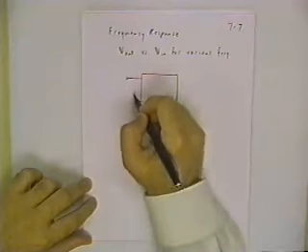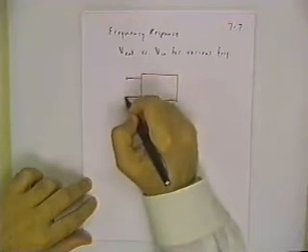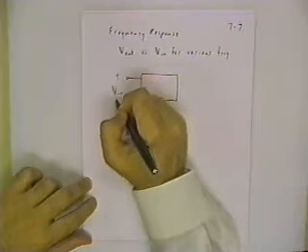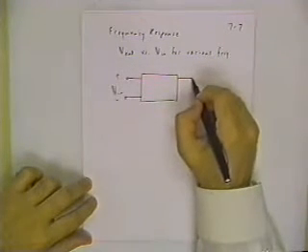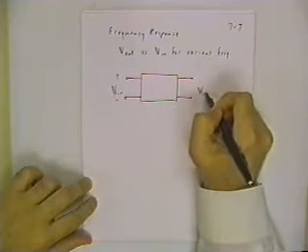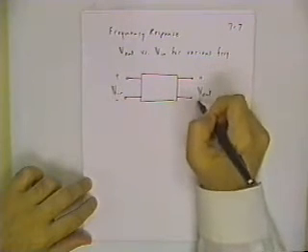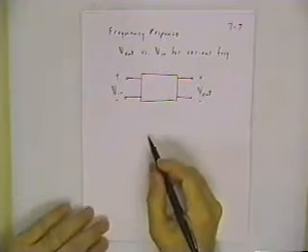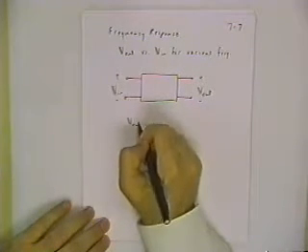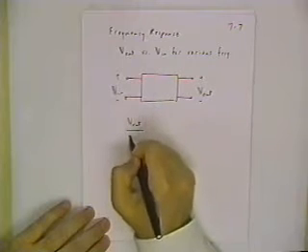At 2 points, you're identifying as the input some input voltage. And then at some point in the circuit, you're probing the output with a voltmeter or an oscilloscope or some other measuring device. And what you do is set up a ratio of V out divided by V in.